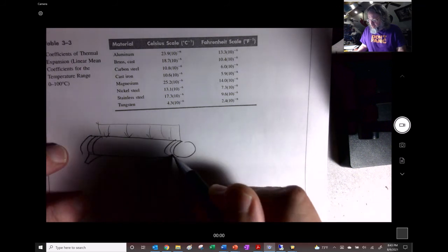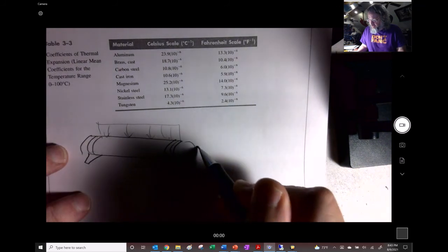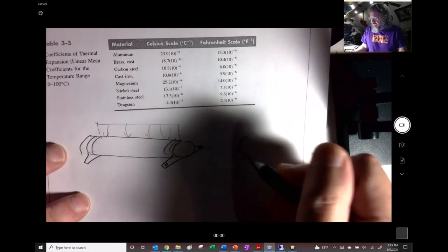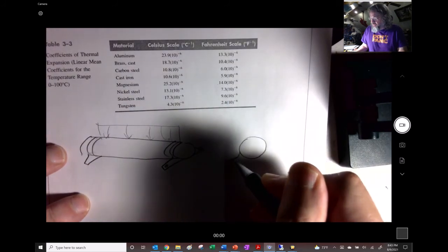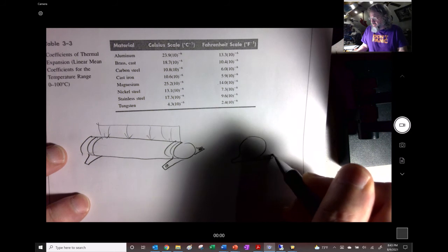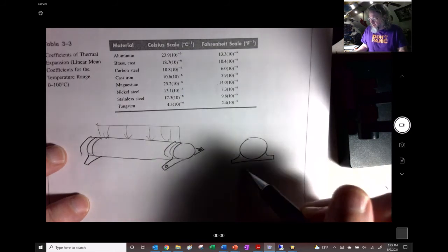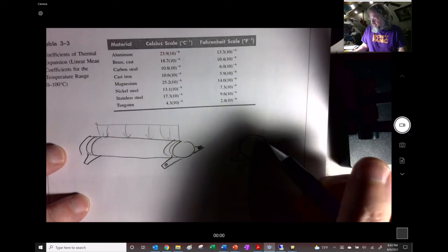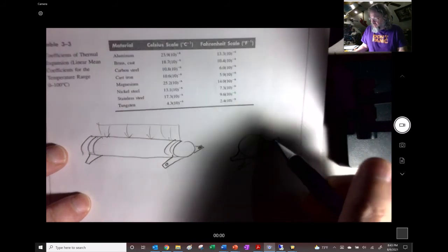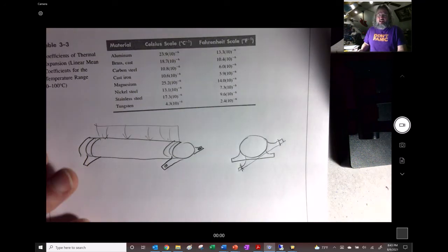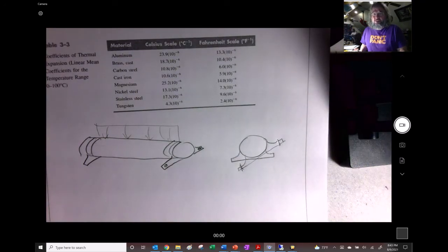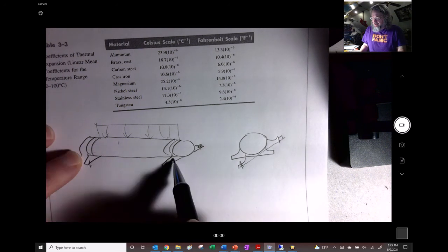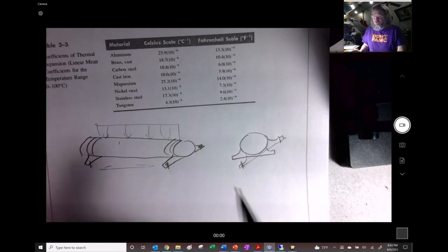And I made the mounts look like this right here, so you could see that it was mounted on these spots. And somebody had fabricated it poorly. So on one end it was like this right here, but on the other end, for some reason, somebody had misaligned the other end, right? And then they clamped it down really tight. And not only did they clamp the thing down tight, when they clamped it down tight, it wasn't allowed to expand.